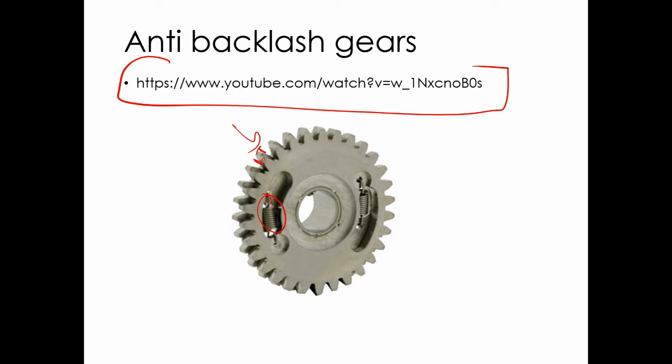And so if your torque is high enough to compress those springs, you're going to get some backlash, right? There's going to be play in the system as these two gears move relative to each other. So they're smoother, they're quieter, but you still have backlash because it's a spring rate, right? They'll be preloaded at some point, but when you're moving a lot of torque through these things, you're going to stretch these springs out, and it's going to be hard to get a spring with enough preload to completely eliminate backlash.